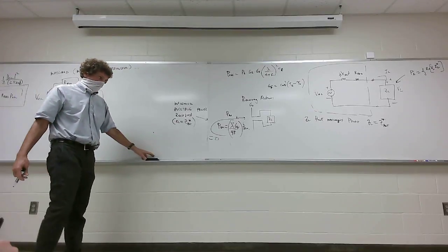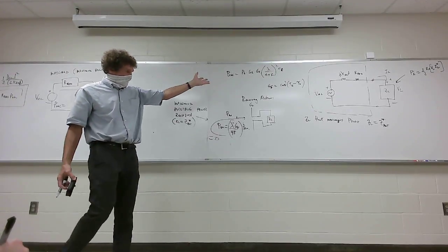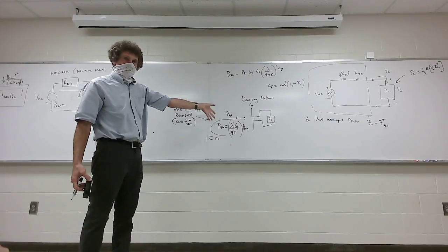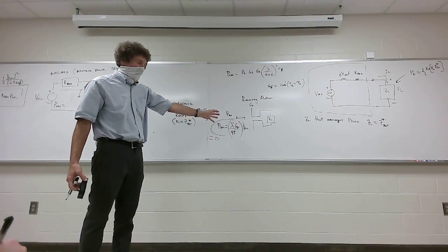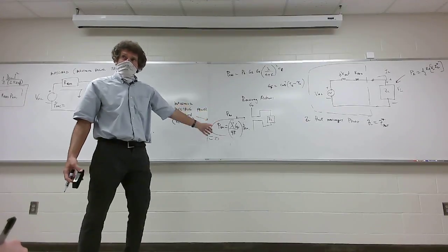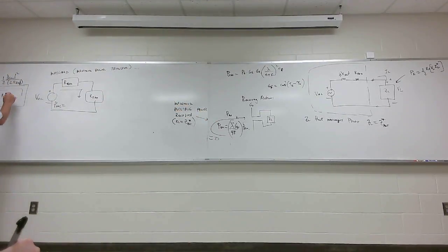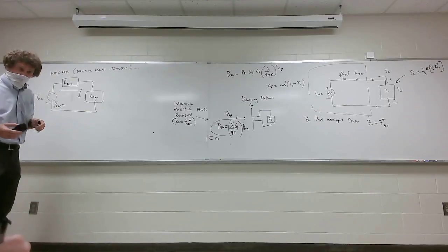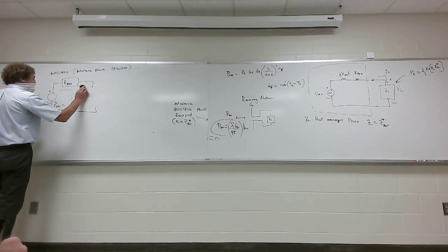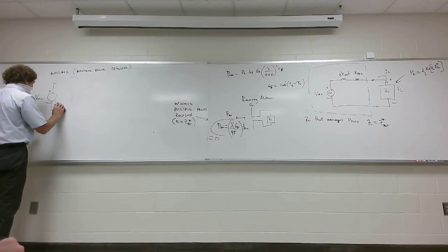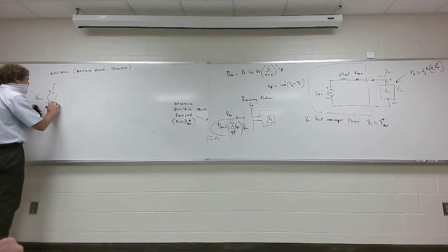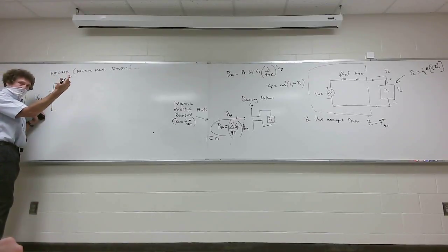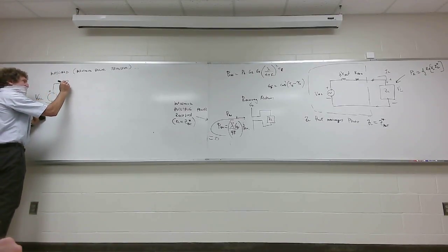So here's the thing. I found the power density incident on the receiving antenna. I multiplied it by the area, lambda squared over 4 pi times the gain of the receiving antenna. I find the total power received. That's this quantity right here. Now I get the open circuit voltage. And now if I put on any possible load, remember this was ideal, then the circuit I have is this. Remember, now I have the open circuit voltage. Now here's my antenna impedance. It doesn't matter if it has an imaginary part, but its Z antenna is here.